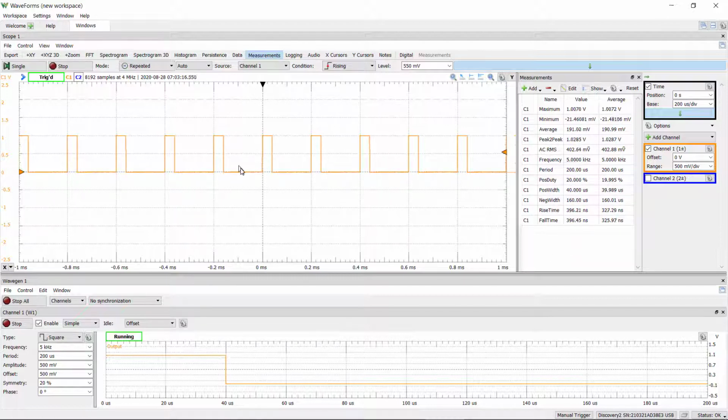If we have a waveform that matches a pattern, an established waveform that we understand, that has certain patterns to it, and we can define those figures of merit based on that pattern, and if that waveform adequately matches that pattern we're expecting, we can use the built-in functions in the measurements in order to extract those figures of merit and instantly get an idea, a quantitative measure of the properties of that waveform. That's the power of measurements.